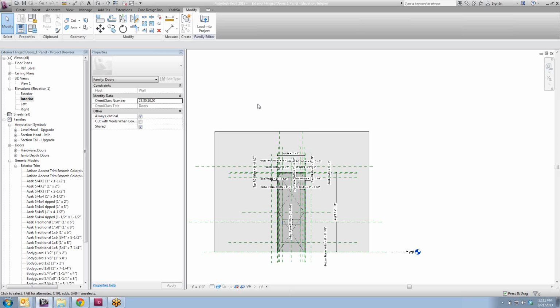I know the way that the BOM works is that there's the interior material parameter, which you're supposed to use to select either pine trim as the interior trim or the white drywall for a drywall return. So if we add the visual representation of that inside of the family as a nested object like the exterior trim is, then the BOM needs to read the material parameter.